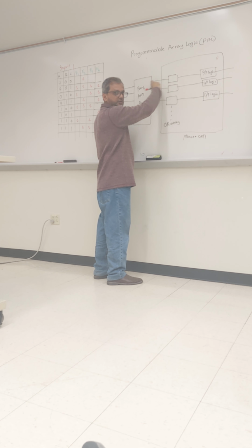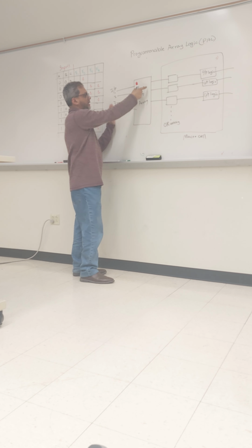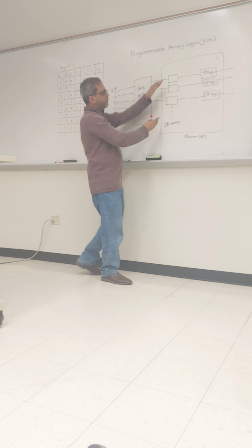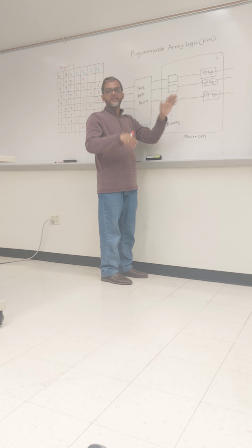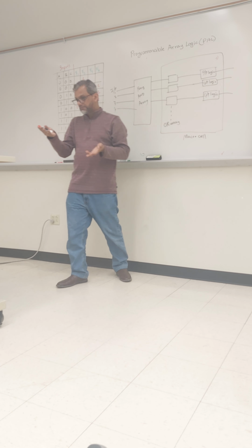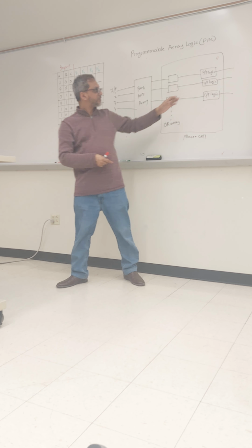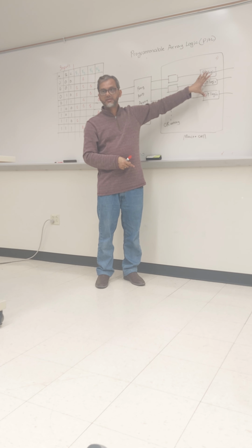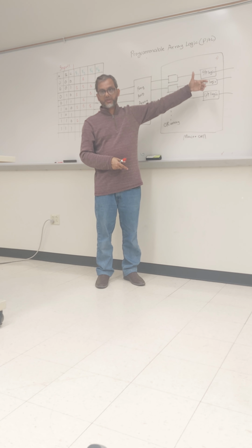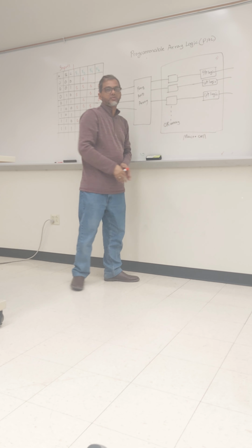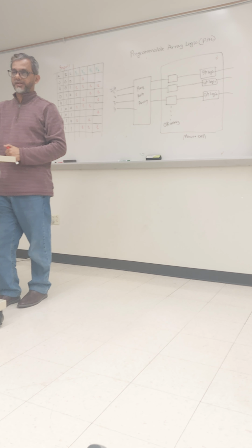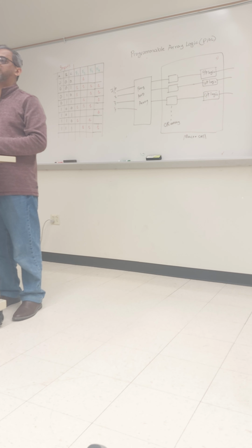We have a fixed connection between the AND and OR, and a programmable AND array. In our last example, we took our output from here. But in the commercial IC, they have some output logic here, like an extra circuit. Overall, this is known as a macro cell, so that it can increase its functionality.